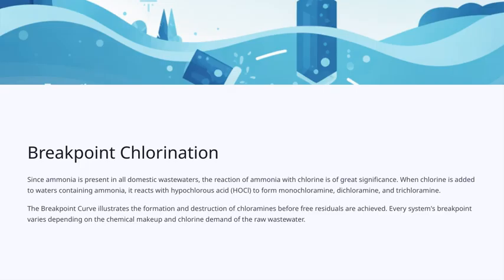It's important to remember that each water system has its own breakpoint. This varies depending on the chemical makeup of the wastewater and how much chlorine demand there is, meaning how much chlorine is needed to reach that free residual level. So, understanding this process helps us optimize disinfection and ensure that we're effectively treating water while minimizing chloramine formation, which ties back to our overall goal of safe and clean water.